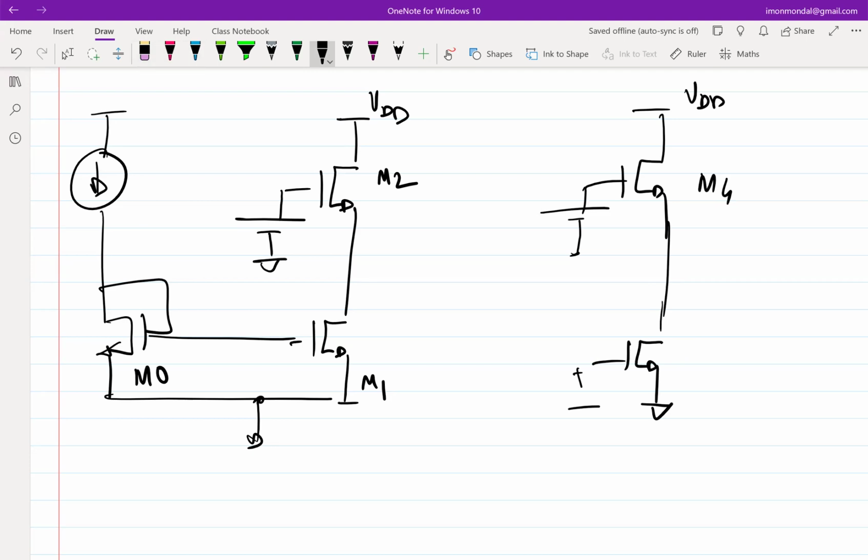So I can essentially say that this voltage is the same that is required. So I can keep drawing. And this I can do because connection of this infinite number of MOSFET gates doesn't load, right? So this IG is 0. Because IG is 0, connecting this does not divert any part of I0 into any of the gates. So that voltage doesn't change. Had Ig not been 0, then it would have been a potential problem.